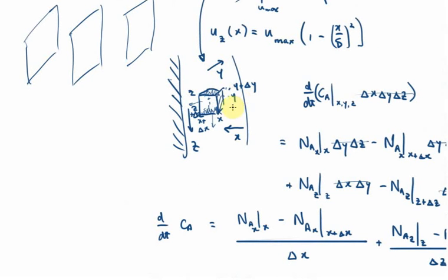Now, if you look in the X direction, we don't really think of there being convection in this direction. You could argue that a film is kind of a free surface, and there is some kind of rotation here because you've got a zero velocity here, no slip on the wall. But in principle, we don't really think of there being flow in the X direction.